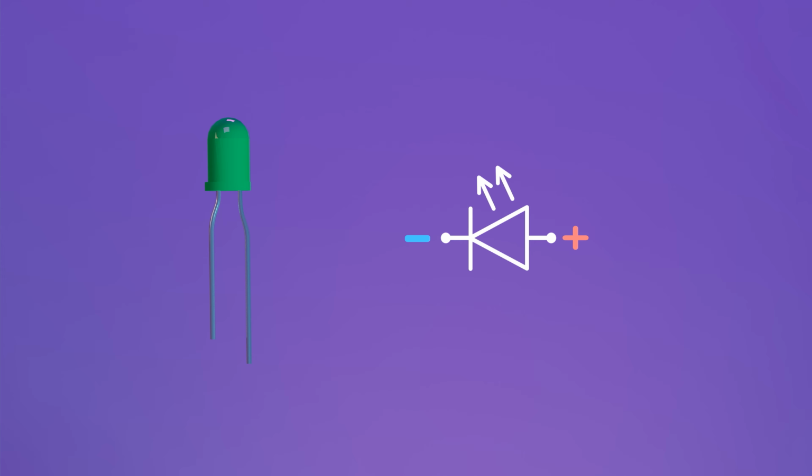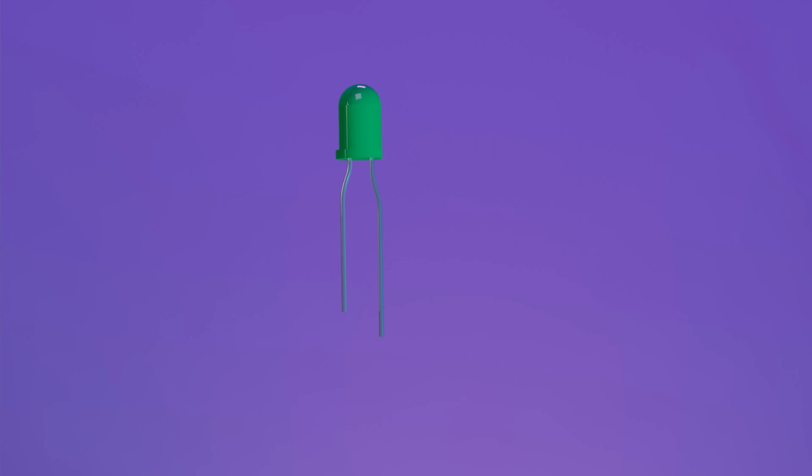To determine where the cathode is and where the anode is, you just need to compare the length of the legs. The long leg of the LED is the anode. We connect it to plus. And the short leg is the cathode. We connect it to minus.